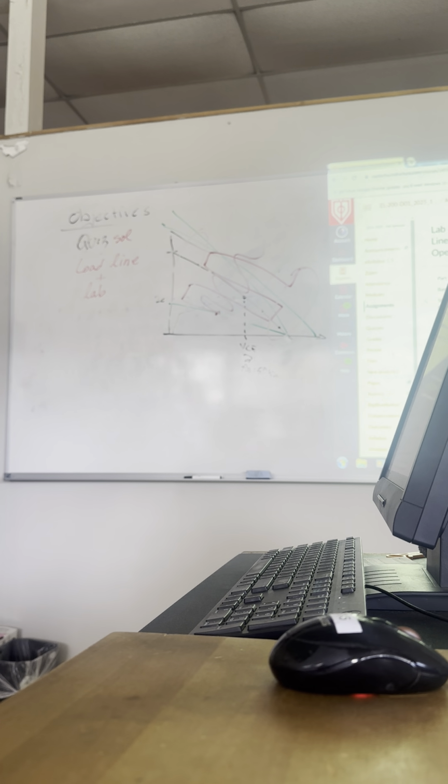Does that make sense? Hey, I'll put a capacitor or an inductor and play around and see if I can create different kinds of filtering with the signals. It's a whole bunch of things you can do with this. If it's an audio amplifier, I want to make sure my amplifier does not saturate or cut off, otherwise you end up with clipping and you're going to lose data. Does that make sense? The voice, the music is on that information. You're not reshaping signal, you're just amplifying. Is everybody with me so far?